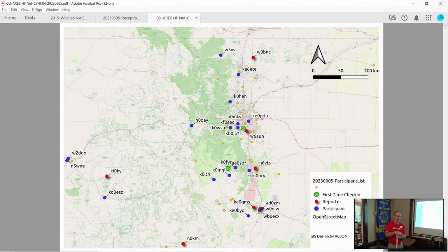And I have a railing on my Xterra. It's an aluminum railing on plastic mounts, and I found out they're isolated. So I took one of the mounting screws out that goes into the roof and replaced it with a stainless steel threaded stud and a cap nut so I can make a ground connection to my roof.